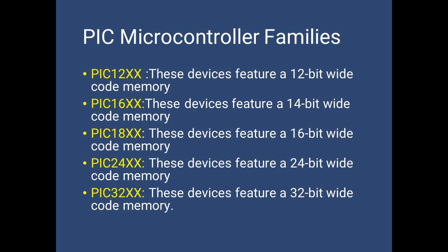Here you can clearly understand what is meant by a different design philosophy. Normally when we design a microcontroller, it is either 8-bit, 16-bit, or 32-bit, in a didactic scale. Whereas PIC microcontrollers have a different kind of philosophy. Even though PIC 12, PIC 16 and PIC 18 are all 8-bit microcontrollers, they do have different sizes of instructions. The same is the case with the 24. Here the device has a 16-bit capability, but its program code is 24-bit wide. So that is a different philosophy.